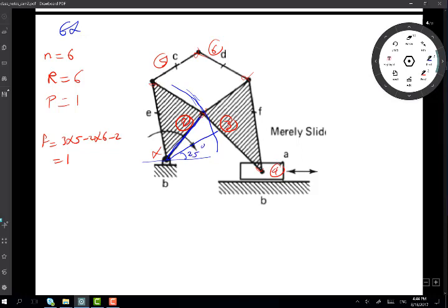So this point has moved from here to there. So what should we call it? It doesn't have a name. So if I call it G, this is G prime, the new position. And then draw the whole linkage when G has moved to G prime, or when this angle theta 2 is 25 instead of whatever it was.